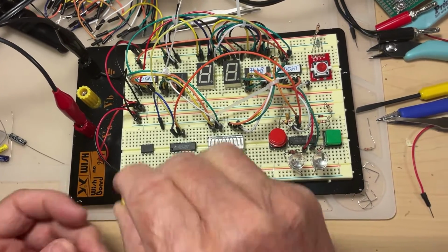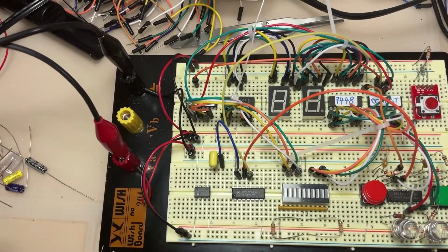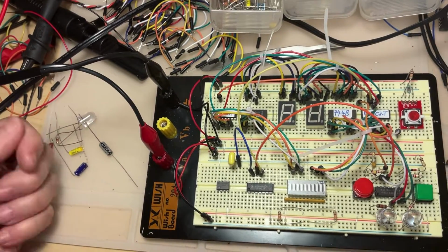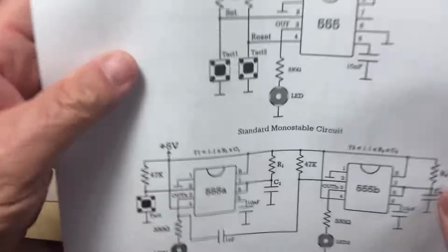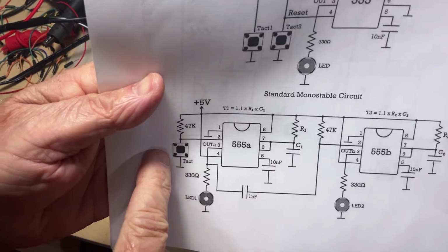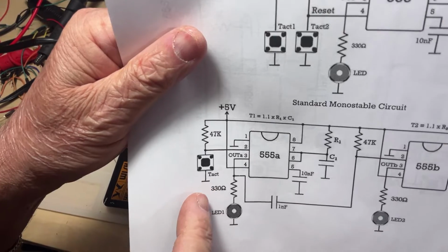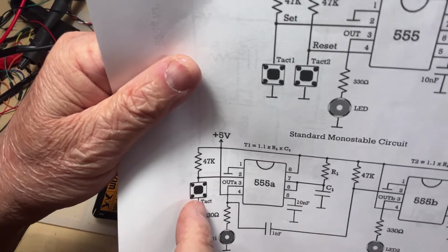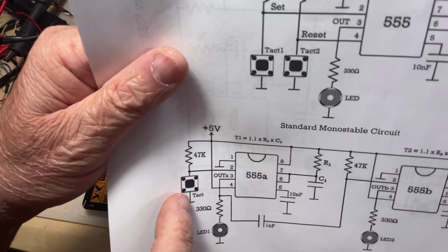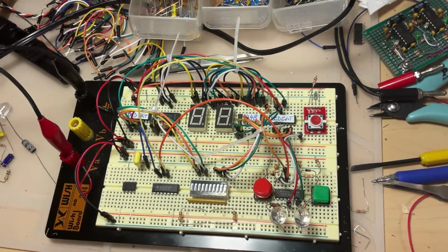First thing I'm going to do, I'm going to decouple the pin 5 to the ground by a capacitor of 1 nanofarad, whatever I have available. Then, instead of using a push button to trigger like here, I'm going to use a capacitor. So in the moment you put the power on, the capacitor is going to suddenly be charged by that resistor here in the top. So you don't need a button to trigger. It's going to be the capacitor charging which is going to trigger everything.